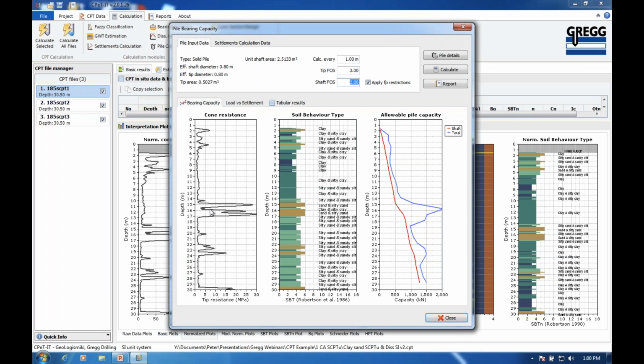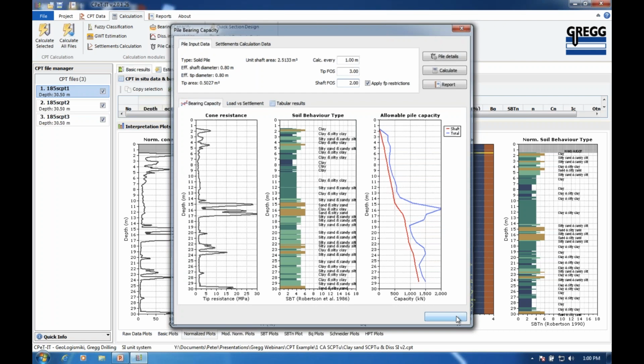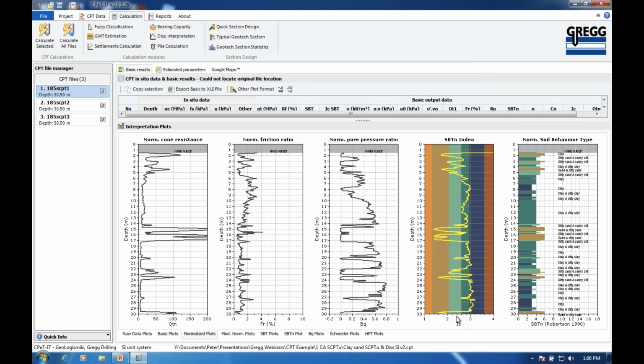So you could drive the piles down to about 15, 16 meters into that sand layer, but the difficulty is you'd actually be sending the load further down and closer to the underlying soft clay. So the settlement of the pile group actually could be quite large because you'd be sending the load further down into that softer clay. So on this particular site, you're probably better to not do that. But you can see that this sort of tool gives you the ability to very quickly look at some of the variables.